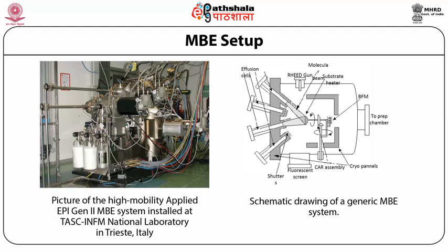Now, as you can see, molecular beam epitaxy has several key characteristics which make it an industry and research standard growth system. It is a versatile technique, that is, it is used to make epitaxial growth films, and abrupt doping profiles such as delta doping, commonly found in high-speed semiconductors, can be synthesized.